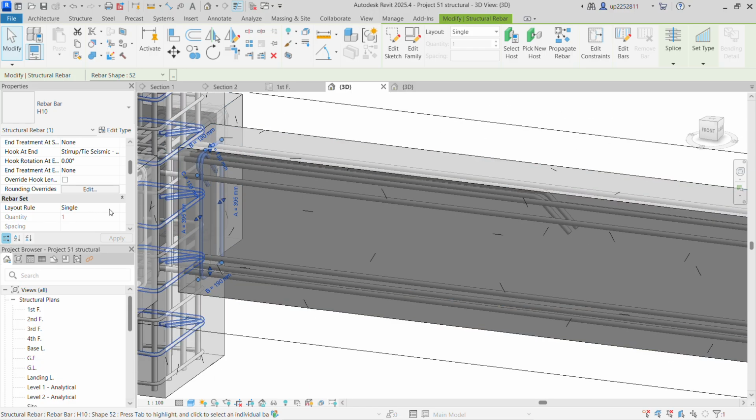Okay, so select the stirrups, press space bar, and then come here, add the rebar set. You will get number with a spacing. First I will keep the spacing 8 inch. The reason behind that I will explain it later. And the bar I'm gonna keep 6.